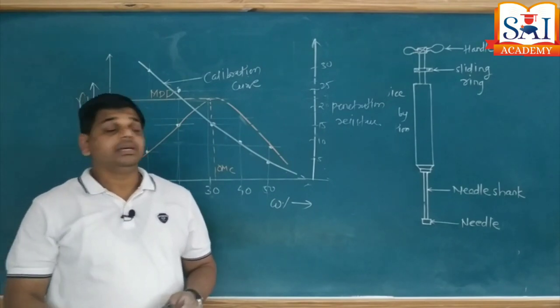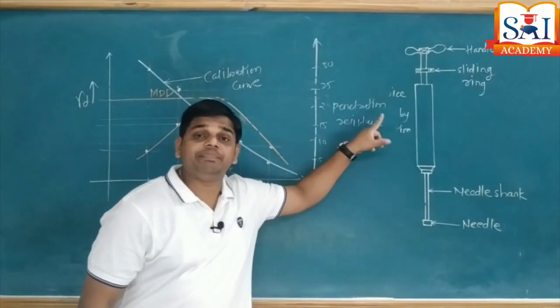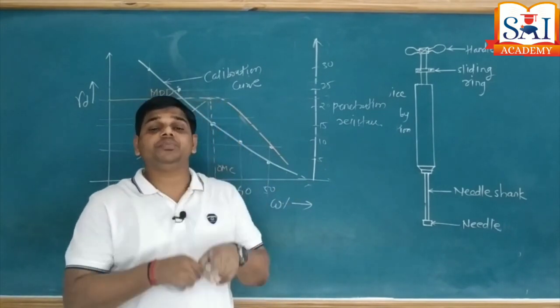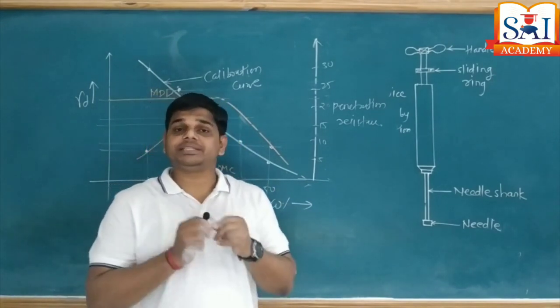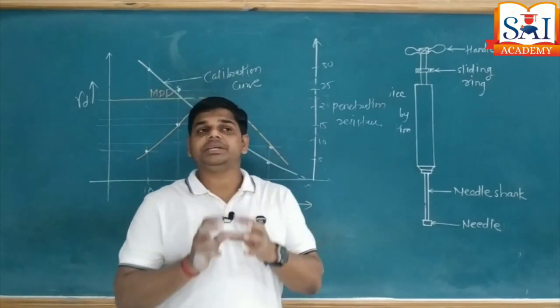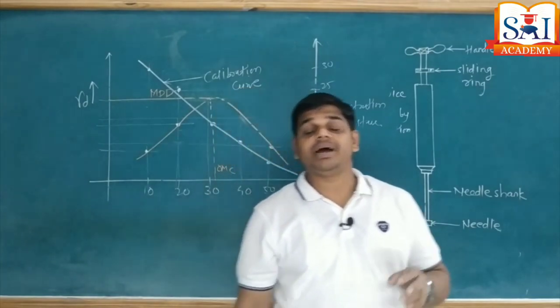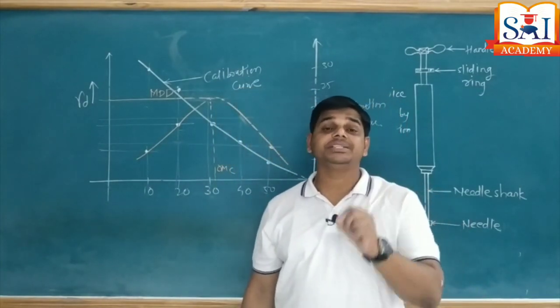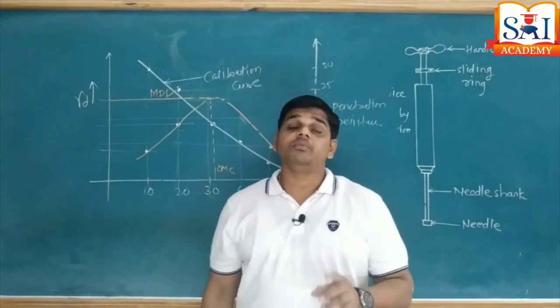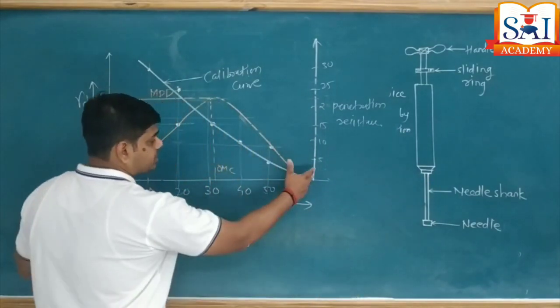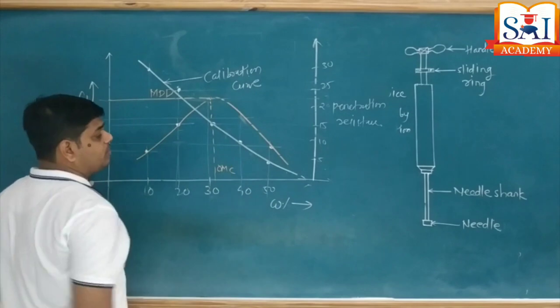in that case take the same needle, and that needle we are going to use to apply the compressive pressure, and penetration resistance is recorded. Now let's see how to calculate the value of field water content by recording the penetration resistance offered by the soil for a penetration needle. Look at the board. We have a compaction curve with a calibration curve also.